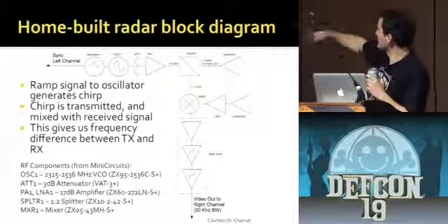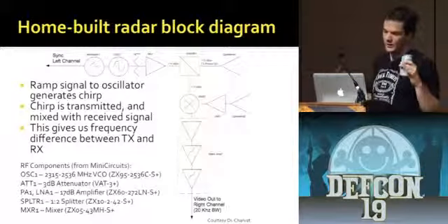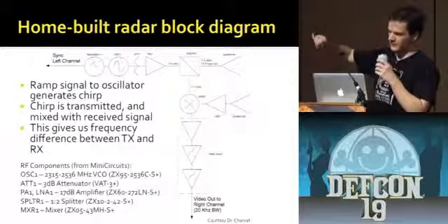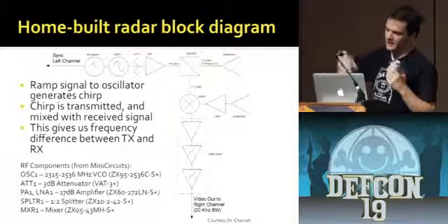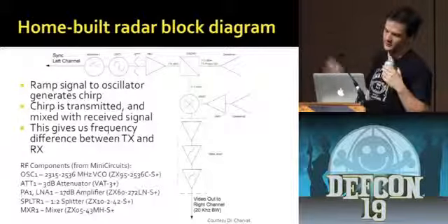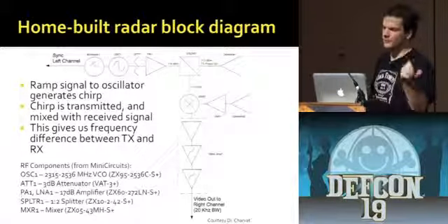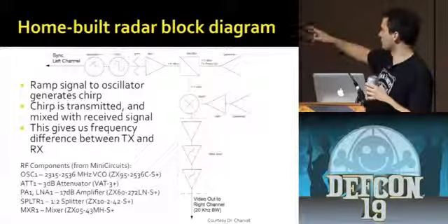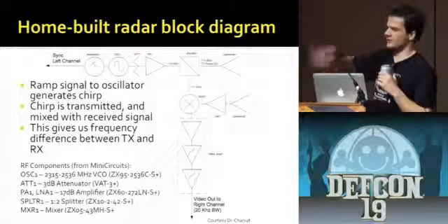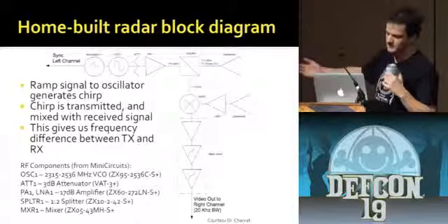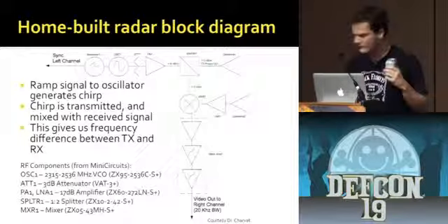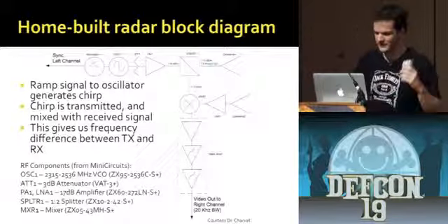And then there's this thing down here called a video amplifier, and what that does is it takes that really small signal and amplifies it a bunch of times at low frequency so we can feed it out to the computer. And there are 2 outputs to this. One of these is the sync pulse, which tells us when the chirp starts, and the other one is the actual data signal back out. And then I guess the components are here. You can get the slides later.